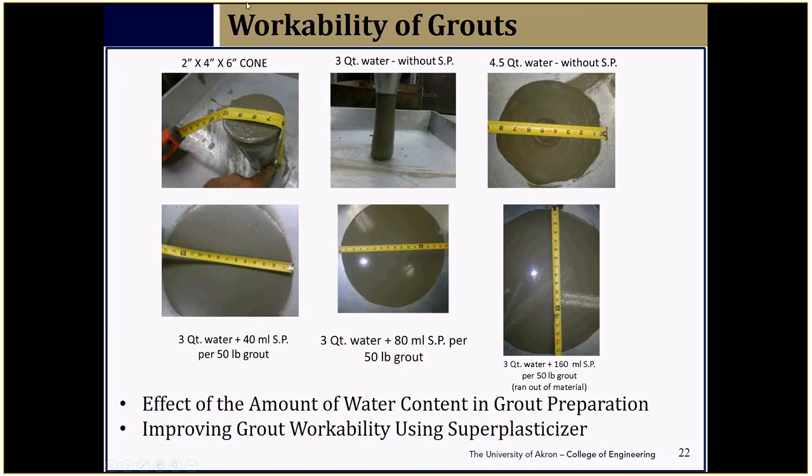I'll show you some pictures of the actual construction practices. The manufacturer says, just add water. That's what it says on the bag. So that's exactly what the contractor does. He just adds more and more water in order to make it flowable. And it's understandable, because with this kind of workability, you cannot place the mortar in the very narrow opening of the longitudinal joint.